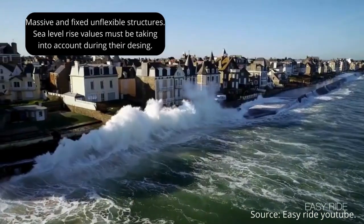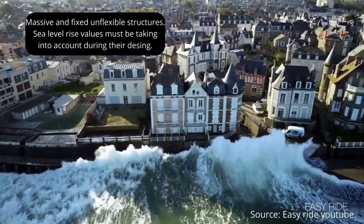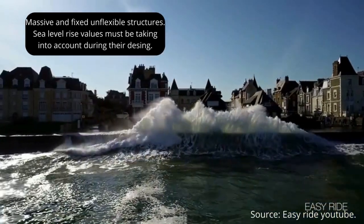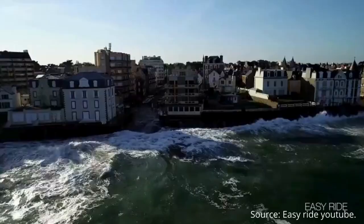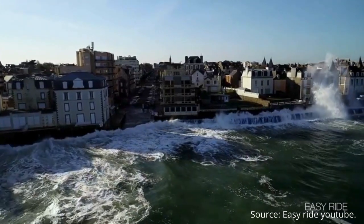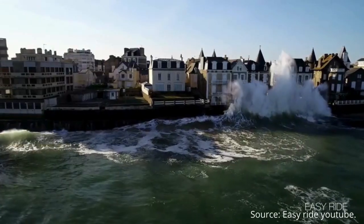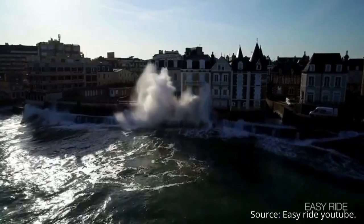Seawalls are normally very massive structures because they are designed to resist the full force of waves and storm surge. A seawall is usually a fixed, inflexible structure, and therefore future sea level rise must be fully accounted for during the design phase. The philosophy behind the concept is that storm erosion will be prevented by simply cutting off the local supply of material. While in a situation without a seawall, even a moderate storm surge will attack and erode the mainland. In the situation with a seawall, this is prevented.